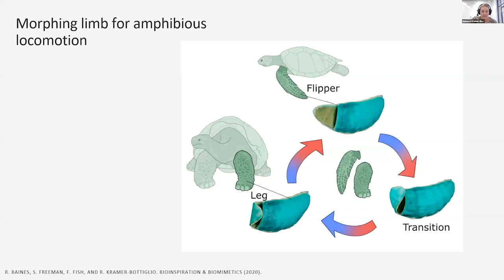So as you can see in this image, we use the laminate to control the morphing of our morphing limb prototype, which is visible on the surface of the limb. So the morphing limb is made of four primary components: fluidic actuators made from channels embedded in the elastomer, variable stiffness material, which is the same thermoset Field's metal epoxy used in the robotic fabrics, a flexible heater made from laser cut copper, and the anisotropic fibers composite used to direct the forces of the fluidic actuators.